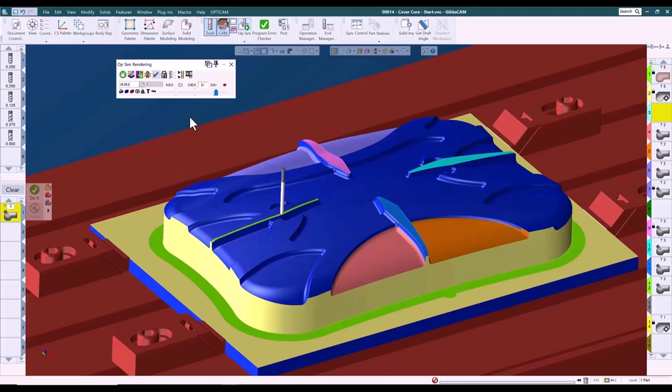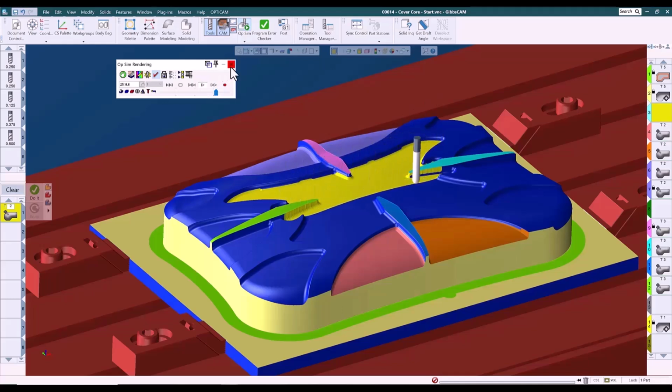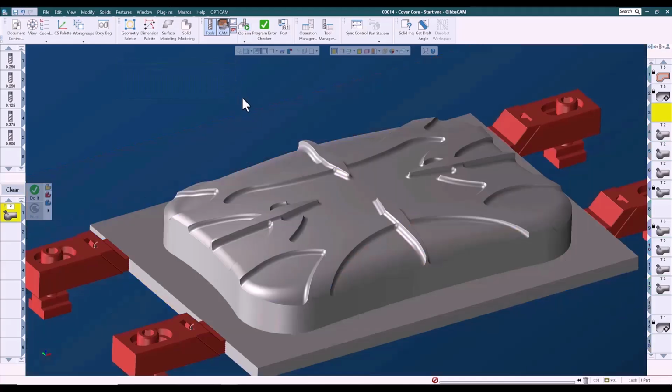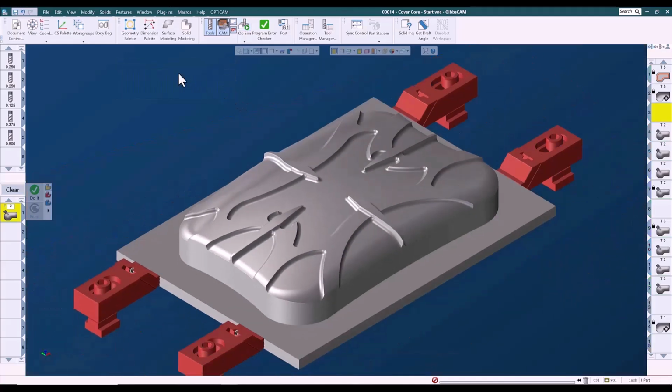Additionally, the multi-axis module provides the ability to calculate various toolpaths based on different underlying technologies, such as a triangle mesh, which is the strategy most widely used in the industry, since the toolpath is a little simpler to calculate and it calculates a little more quickly. But toolpath can also be calculated based on the actual surfaces or based on a geodesic mesh, which tends to produce a smoother, more consistent toolpath.